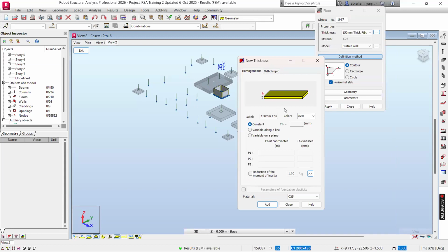When I attach it to the foundation, the software will identify that the slab I've attached has properties of foundation elasticity. Within these properties, there is the geotechnical information that you have to adjust as we've done so that it meets the different soil layers beneath this slab. So the software understands that you're bringing in a slab that is in contact with soil.